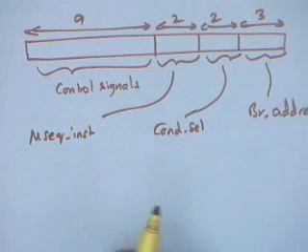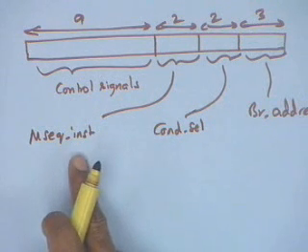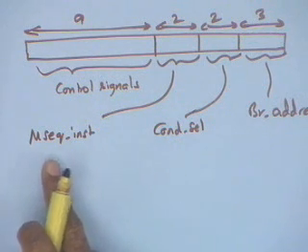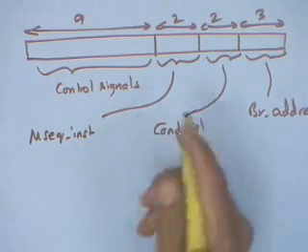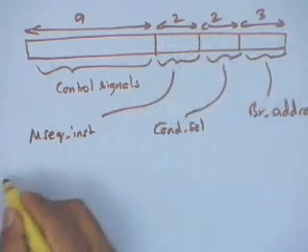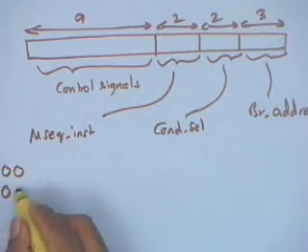The next step that is required is I have to define my encoding. I have 3 microsequencer instructions, and I have 2 bits to store them. So I have to say what is 00, 01, 10.